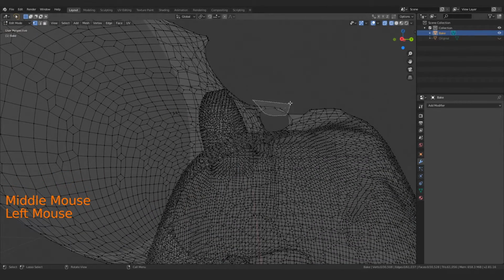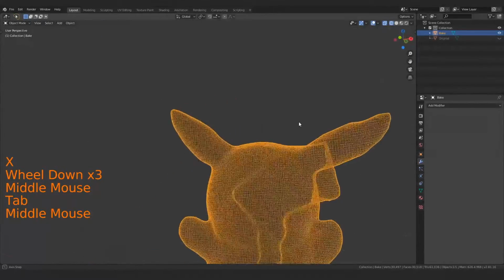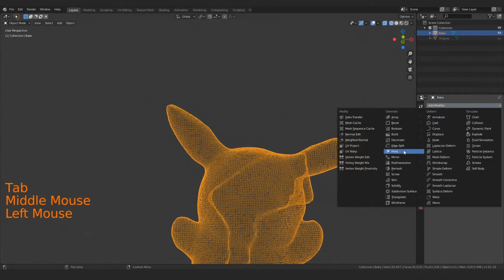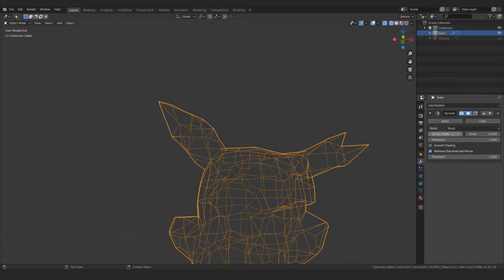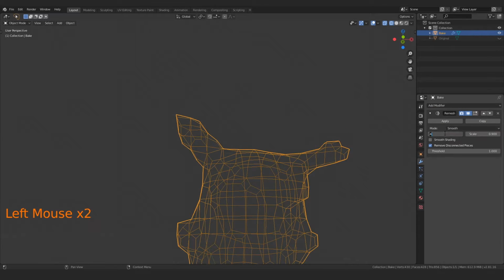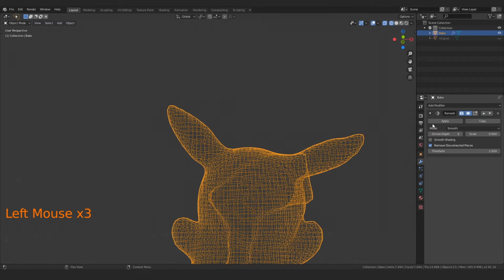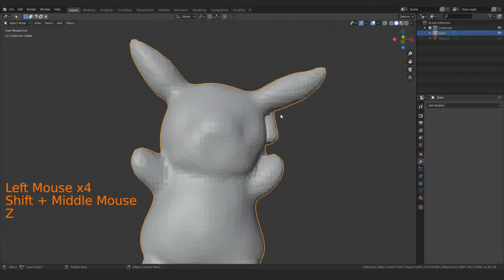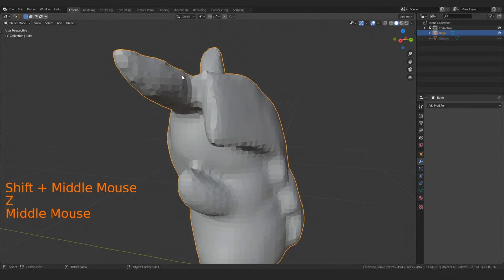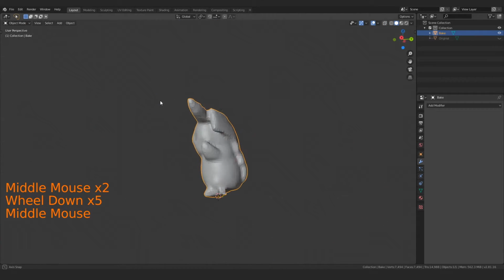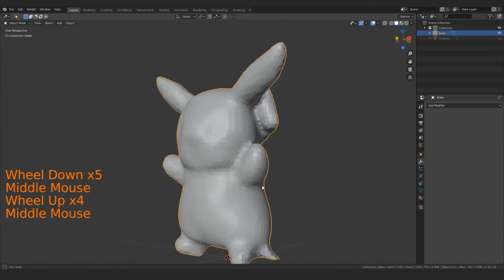And that can happen sometimes with the remeshing option, so I'll delete that. And then I'm going to throw another remesh modifier on top of it to close everything up and make sure it's all hunky-dory. So again, I'm going to go smooth, set this up to 7, and maybe even just 6 this time, and that's fine. Apply this. And you'll see now it's fixed that weird setting there. And again, I could go through and smooth this again if I really wanted to, but this should be fine.